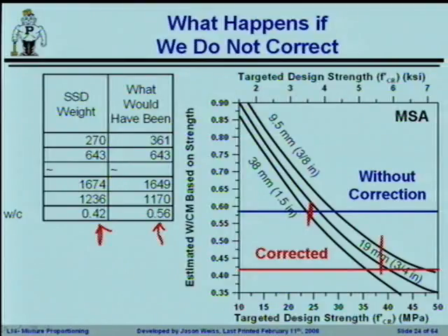Mike? Since our original weights before we did the adjustment were for a specific volume, when we adjust the aggregates in the water, what happens to that volume that we specifically designed for? Like 1 cubic foot of concrete, we get these weights and then we adjust. Is it still going to be the same? What we're just doing is re-partitioning where the water's coming from. The volume should be the same.